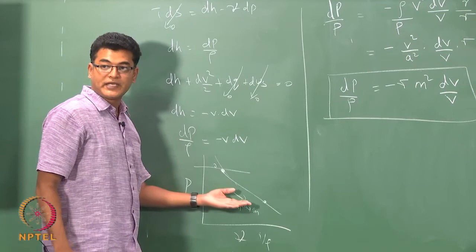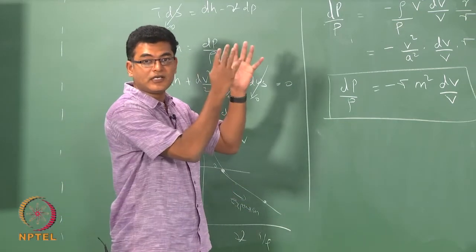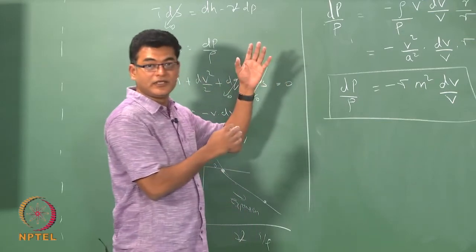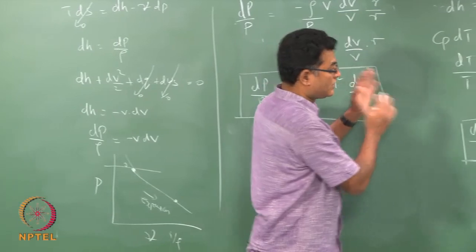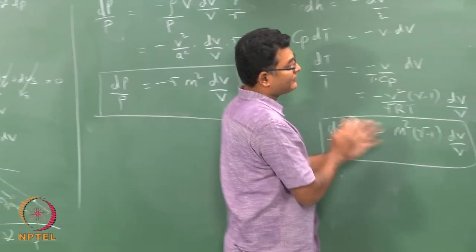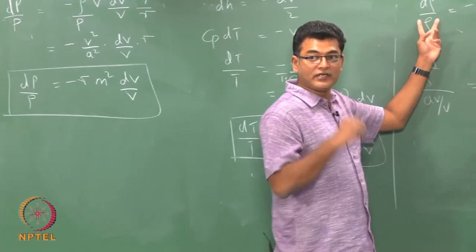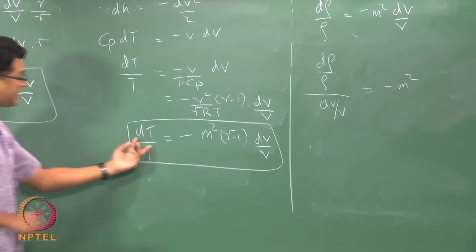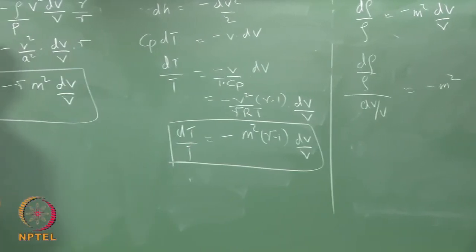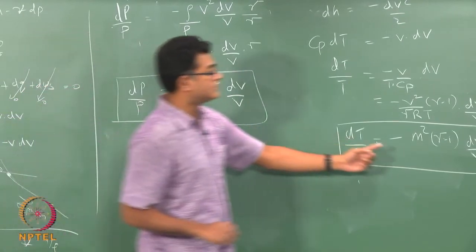This is an isentropic expansion where you are getting your velocity from your total enthalpy, which we had seen to be Cp T0. That enthalpy is going to produce a fractional change in velocity. In the process, you are going to decrease your density, whereas here temperature also decreases, your pressure also decreases, because there is a minus sign associated with this.